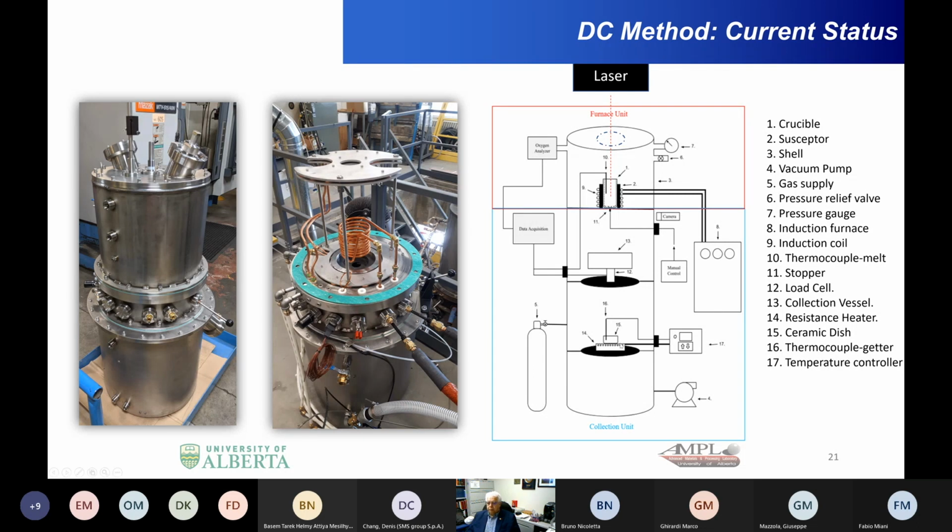One additional improvement: we're putting in here an oxygen getter, where we put some titanium chips over a heater to be able to control and reduce the oxygen content to a prescribed known level.